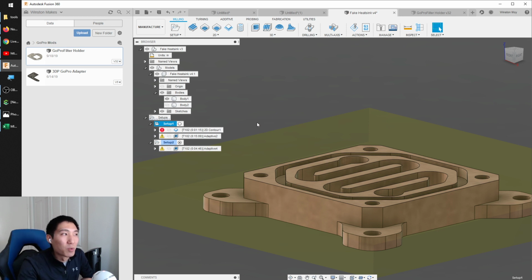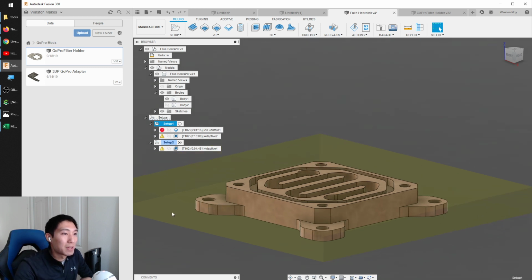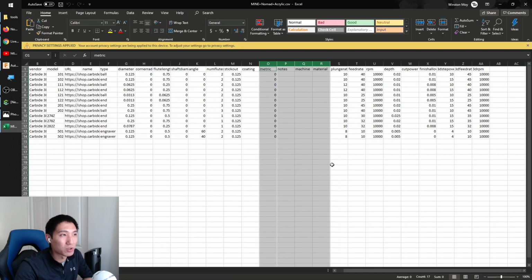So the speeds and feeds that we have are really just middle of the road speeds and feeds that are general purpose. Since I came up with these, I can tell you that my motivation was to go for a slightly larger chip load. So you go a little shallower, but you go faster, so that you're taking a larger bite out of the material. And in plastics and metals, that's a lot more helpful because that helps sequester heat in the chip that you're making.